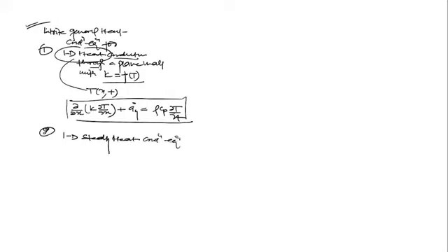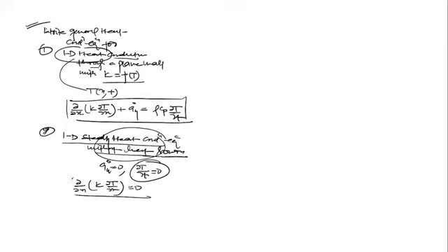One dimensional steady state heat conduction without heat source. So without heat source means q is equal to 0. Steady state means del t upon del t is 0. Temperature will not vary with time. No accumulation term is there in steady state. One dimension means only the term del upon del x. But k is a function of temperature because they have not given any information about k. So del upon del x into k into del t upon del x is equal to 0. Is this clear?